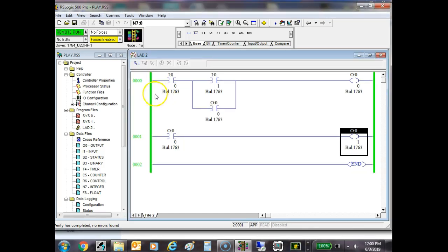So right now it shows me here's my power rails, and they both come up green. See that? What I'm going to do is come up to switch 0, which is going to be our stop button, and I'm going to turn it on all the time. This is simulating what we call a stop button. And notice it went green, which means now it is true. Okay, and what's it waiting on? Input 1. It can't get anything from this, so this is an output.